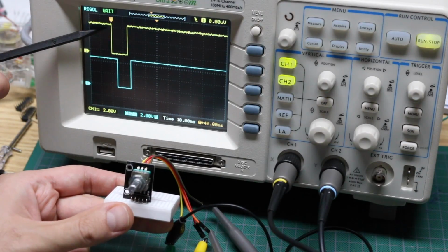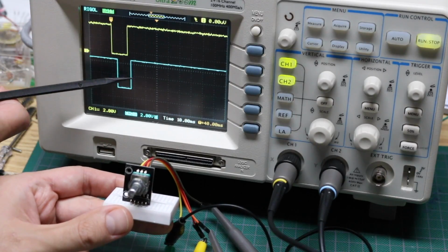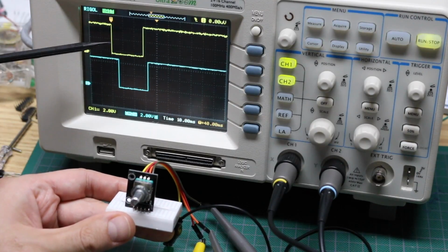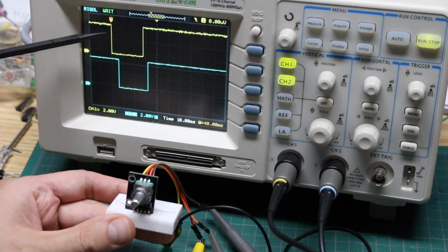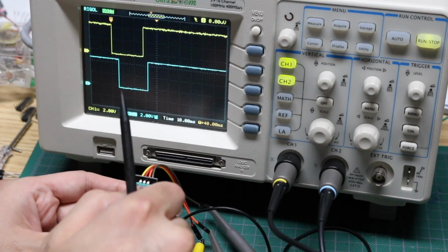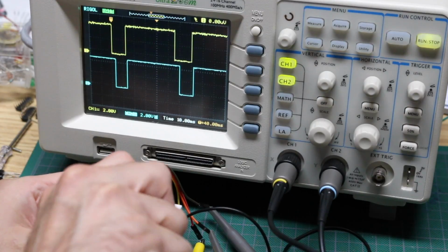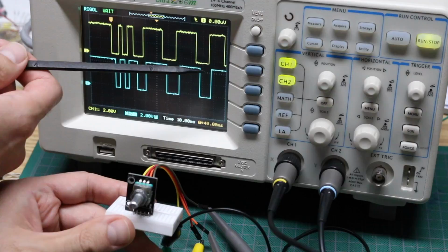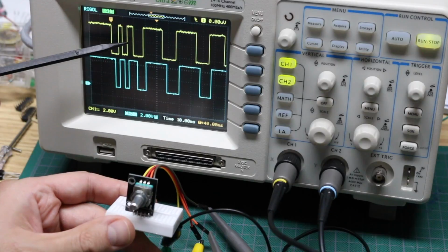And it does. A dropped, and then shortly after, B dropped, and then A went high, and B went high after. Do it again. So this one was a slower rotation movement, so it took longer. A drops, then B, A rises, then B rises, going clockwise. If I go faster, I get a couple of those. If I go really fast, luckily I did not get any contact bounce. I do sometimes get contact bounce, but this looks relatively clean. So A keeps going low first. And then we rotate again and again.